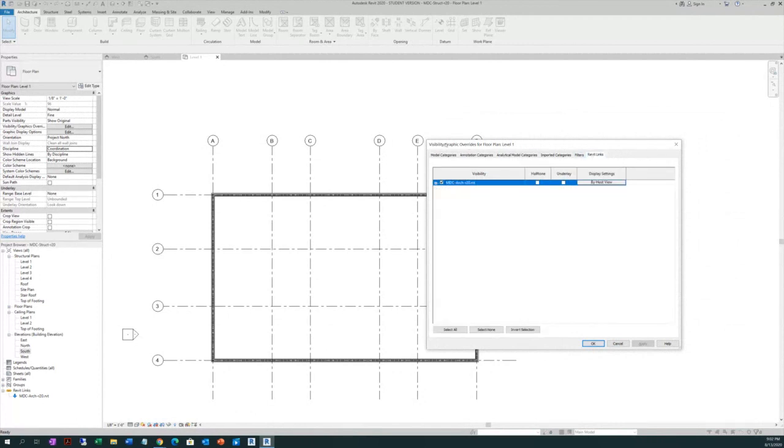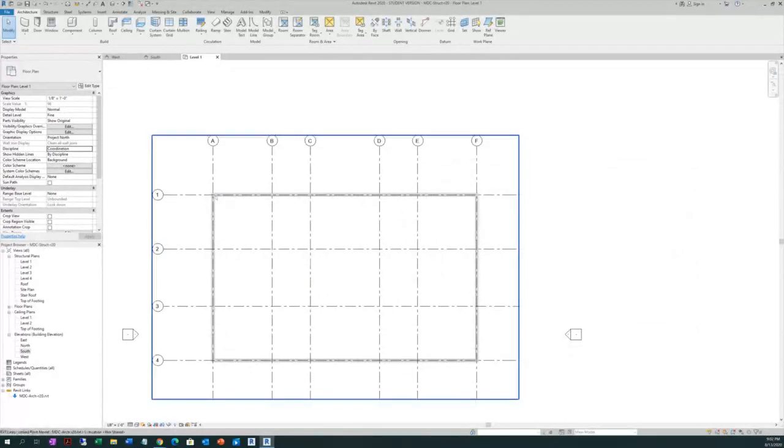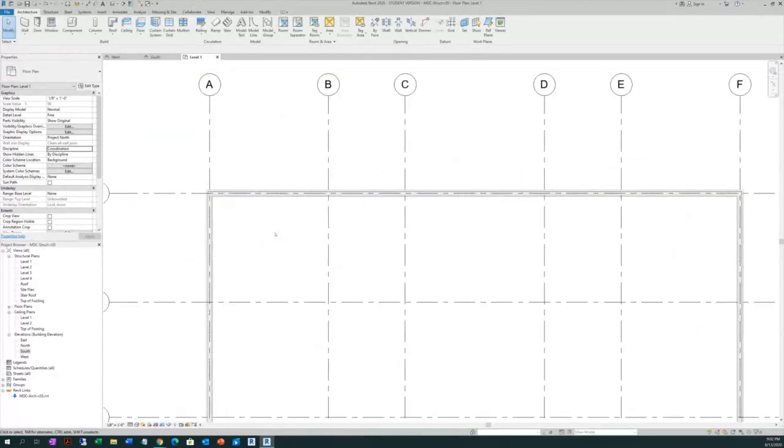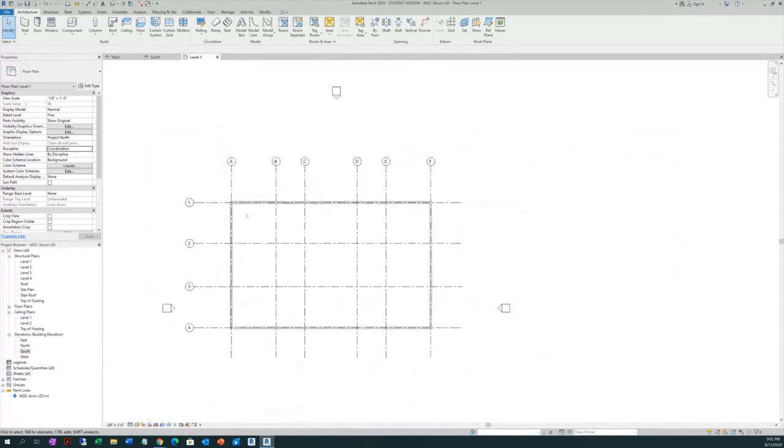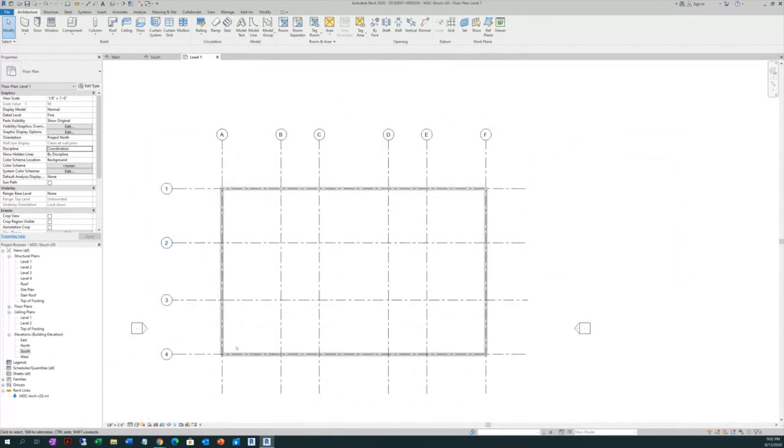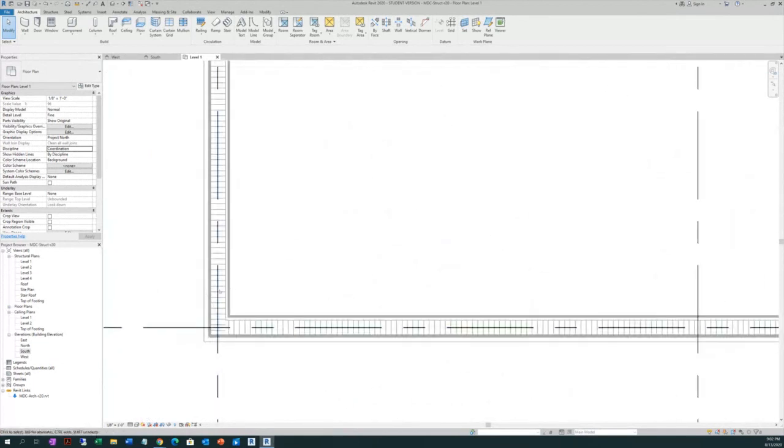Revit link on the visibility graphic for Revit links, and just put that architectural file on halftone, so it doesn't bother you when you are placing your real wall now. See, we can have that, correct? Now, something like that we have, and you know that this is the stack wall.